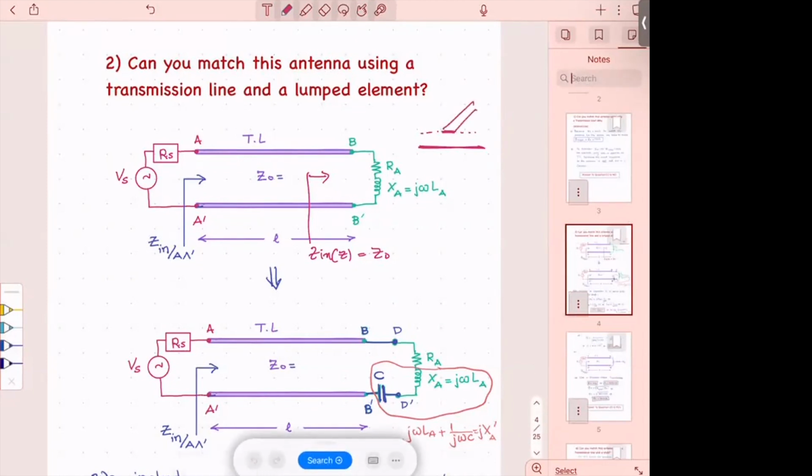If you tell me that the width of the microstrip is like 10 microns, with silicon, for example, or silicon oxide substrate, so that the Z naught of this line is 50 ohms. If that were 10 microns, and then you find a length which is 1 nanometer, it's not going to work. Or even if you find a length that is 10 microns, it's going to look like a little square. So you have to add something to make it reasonable.